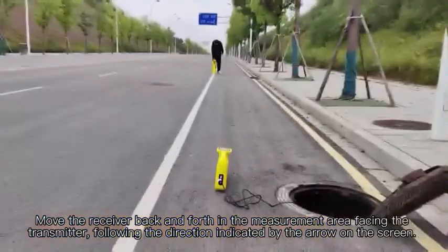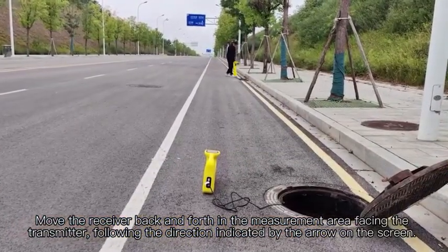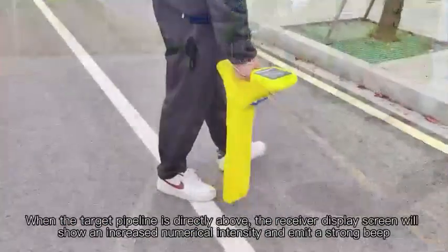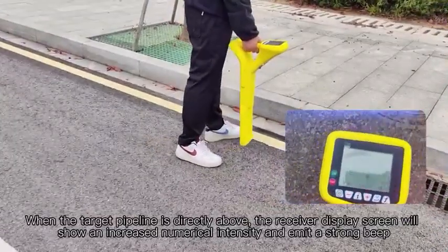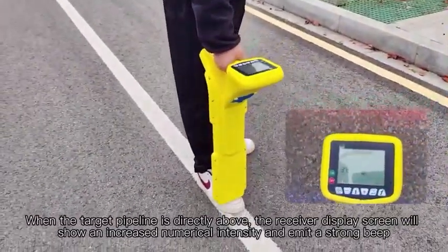Move the receiver back and forth in the measurement area facing the transmitter, following the direction indicated by the arrow on the screen. When the target pipeline is directly above, the receiver display screen will show an increased numerical intensity and emit a strong beep.